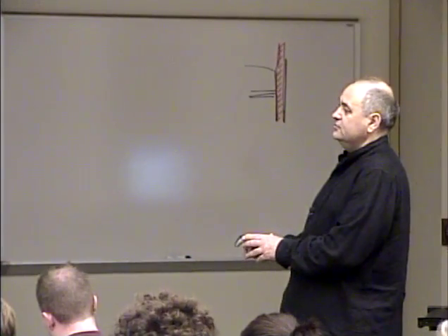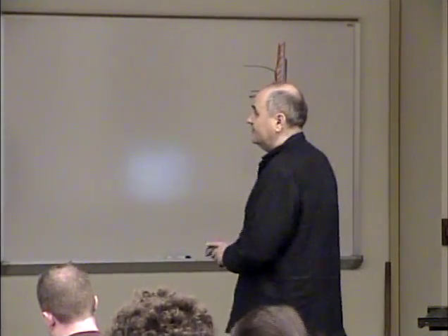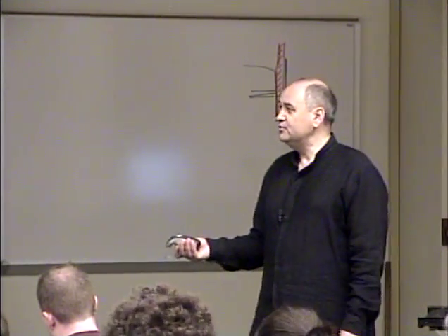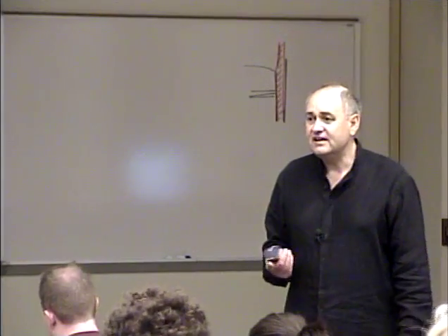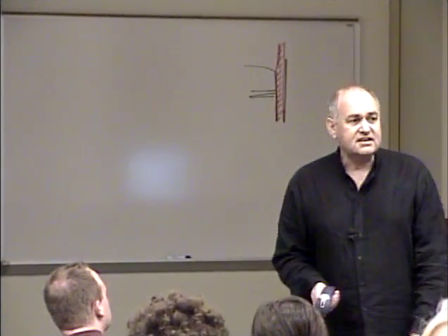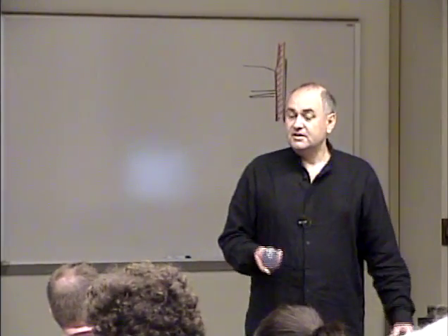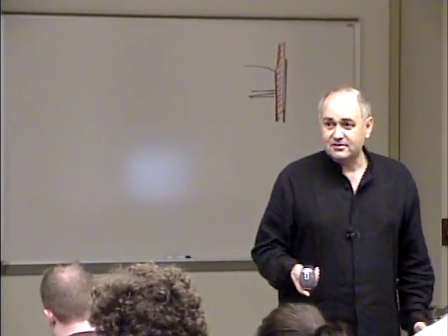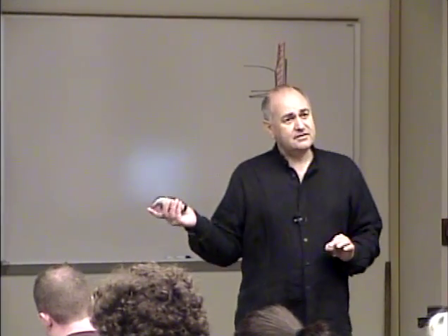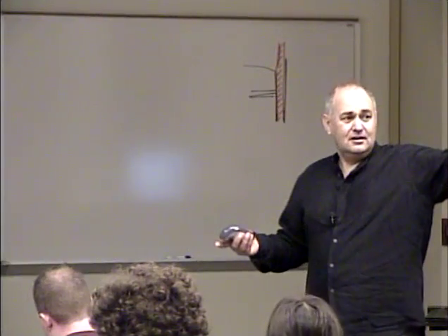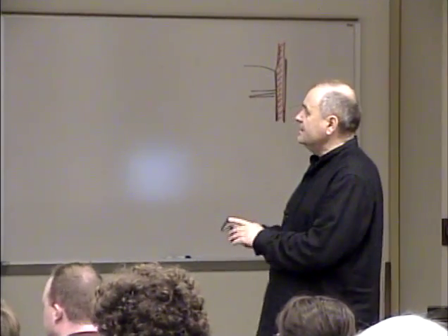So let's now try to determine what is the value of a pressure at a particular depth of fluid, and on top of it, that fluid is even pushed from the top, which actually happens all the time. If you think about a lake, are we pushing the lake from the top? Well, we are not. Is anything pushing that water in the lake from the top? Yes, what? The atmosphere, correct. The atmosphere is pushing it downward. So what you see over here on this drawing is also applicable to a large container of fluid like a lake.